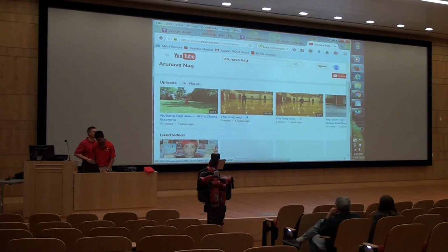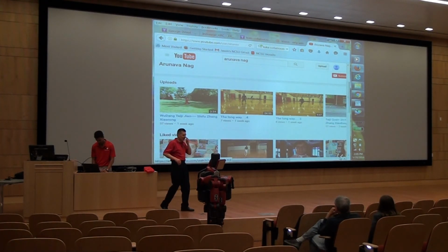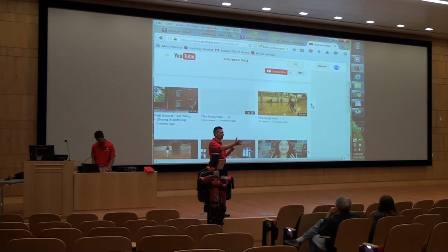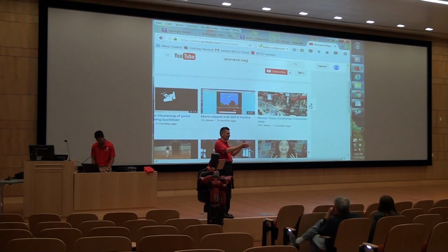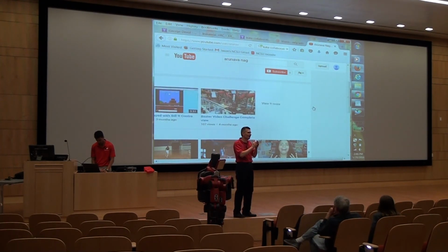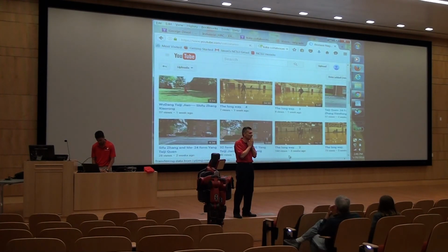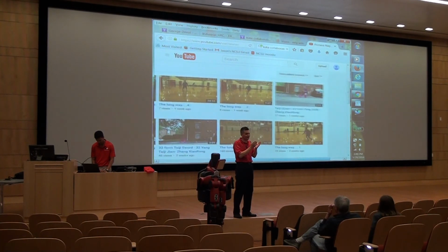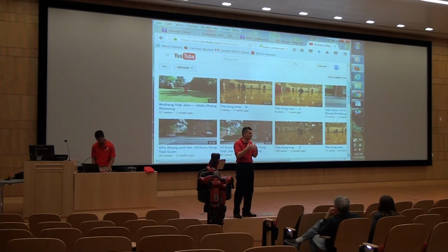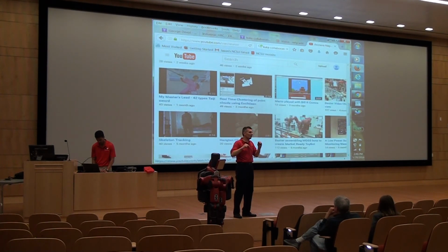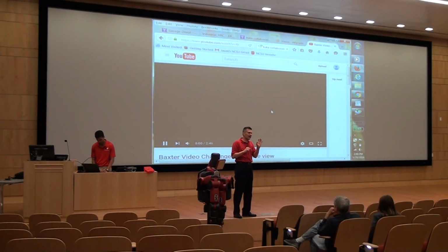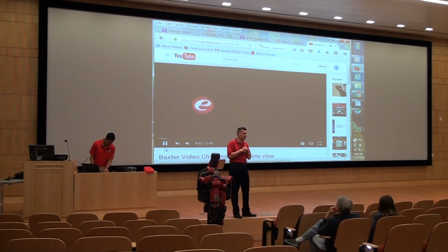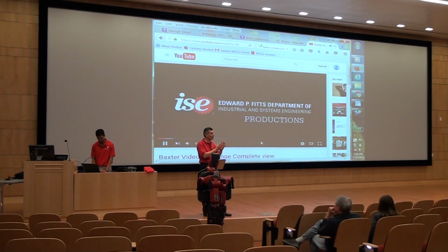Quick question. What's the XYZ accuracy? So there's no published accuracy. Robotics companies hate to do that because they're afraid you'll hold them to it. So repeatability is more the question with a robot. When we first got the robot, going back about 4 software revisions, about a year and a half, we were lucky to get about half a centimeter repeatability, but now we're down to the millimeter range at least, maybe 2 to 3 millimeters repeatability in its work envelope, which is pretty good. But again, that's at very